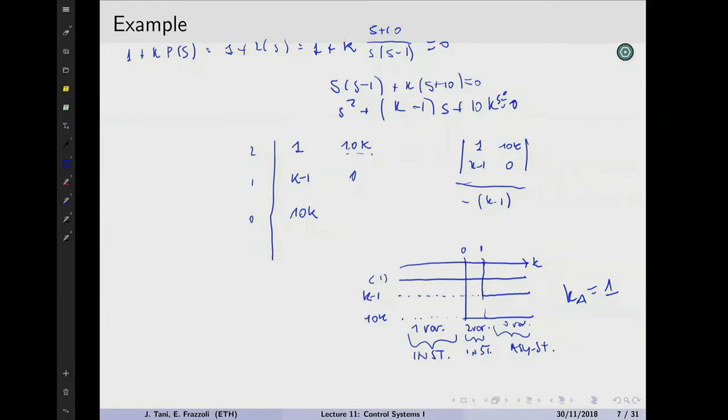This thing here? Okay, so basically, the Routh criterion tells us to take your closed loop, the denominator of your closed loop transfer function. Why? Because that means something to us from a control systems perspective: if the roots, the zeros of the denominator of the closed loop transfer function, have a positive or a negative real part, that means stability or not of our closed loop system, which is the primary objective of a controller. So we look at the first column of the Routh table, and we have to check the variations in signs between the different terms as K varies.